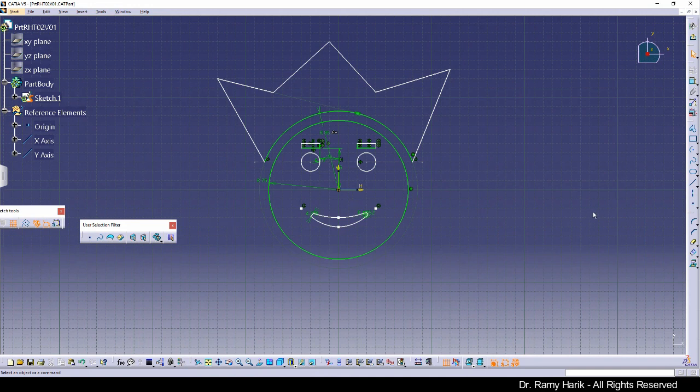The final thing that we want to do is, as we set it, there are several options that you can click in here and see them. One of them, when you click on this one, you can see the capacity to create a polygon and so on. So once again, look at the options that you have. Below the triangle, you have these different options: this is an elongated hole, this is like a key profile, and so on. In here you have different ways to create a circle through 3 points, through tangents. This is for the spline or connectivity. This is ellipses, parabola, exponential, and different elements. This is for the lines, and if you want to create a line that is tangent, like bitangent or so on. So keep in mind you have all of these options.